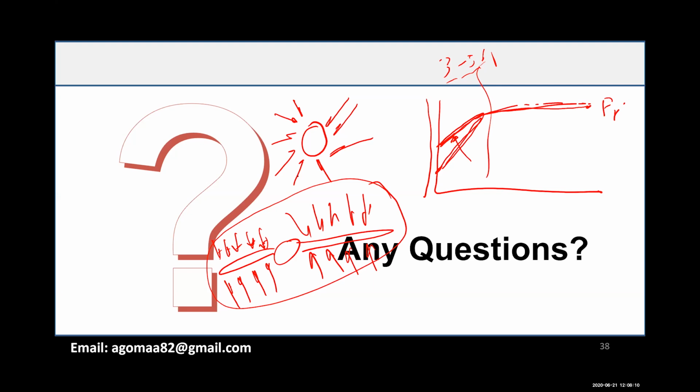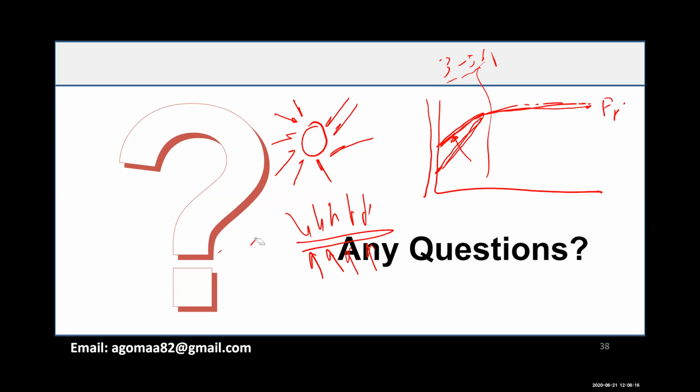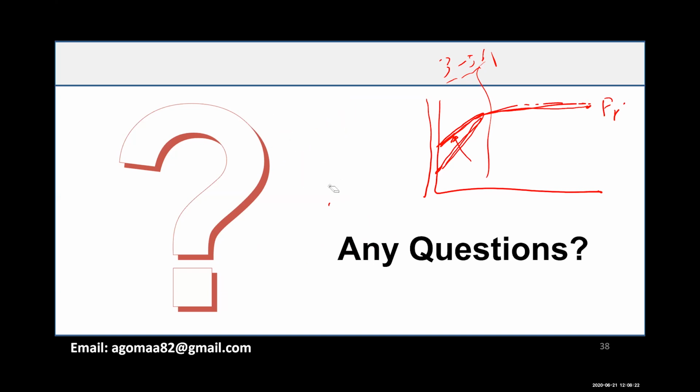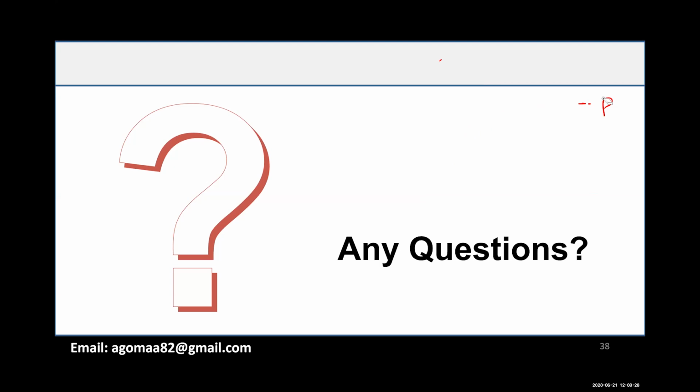Okay, so the next question. You mentioned something about a rapid decline of production as an identification of formation damage. And someone is asking, is it the same for all formation types? I mean, the decline behavior, is it the same for all formation types? Rapid decline is happening when you are plugging either the perforation or the tubing. And that can happen for all types of formation, yes.